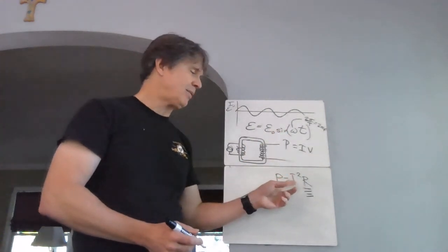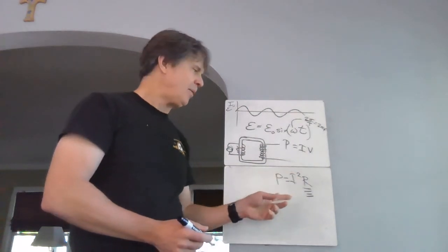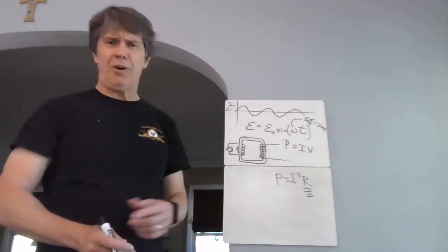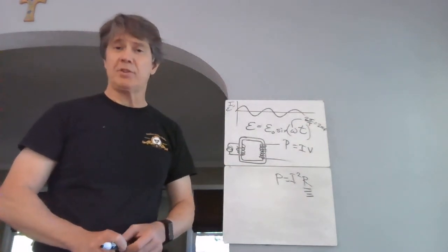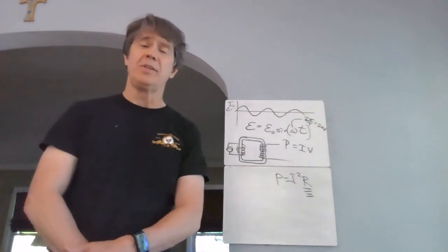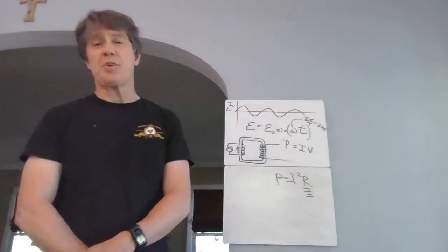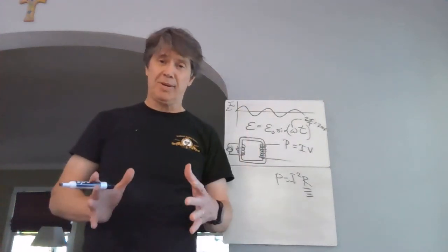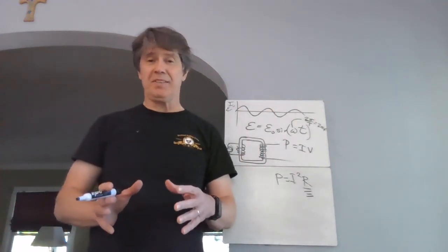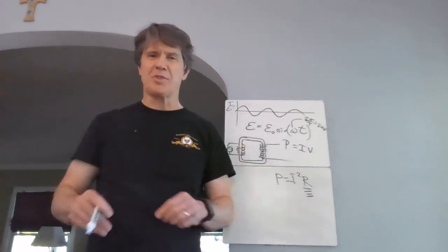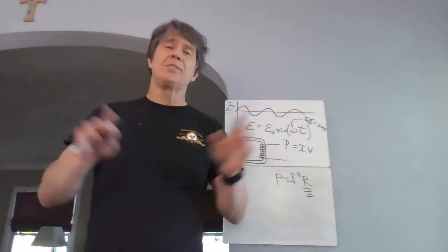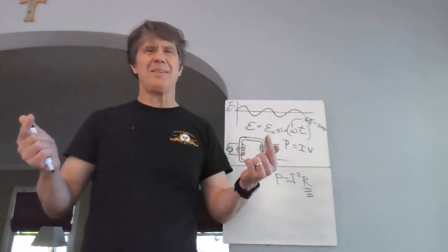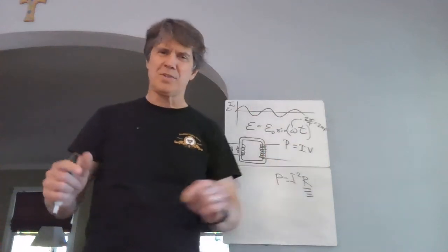And the small current, it's even squared. How about that? Saves hugely in the losses that you're going to have in the transmission lines, and you get the electricity to faraway users. Thomas Edison's DC was no problem if you were just running through about a mile of wire. Like if you had a power generating station in a city, a small city, or a few of them scattered around the city, like in New York, you could send electricity to customers out to about a mile away. Started to get out to 2 miles, it's kind of hard. They aren't getting much anymore because it's used up heating the wires.